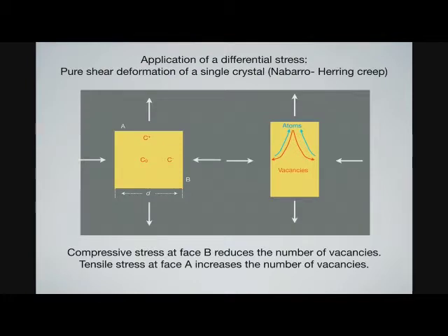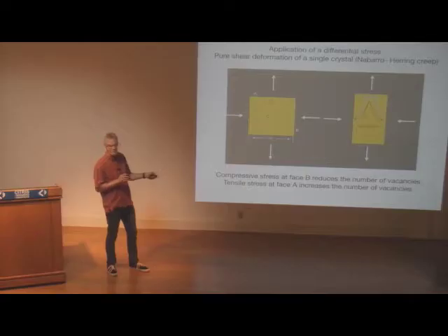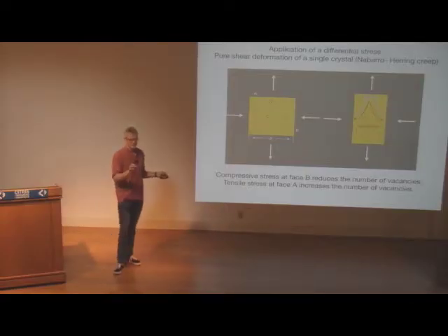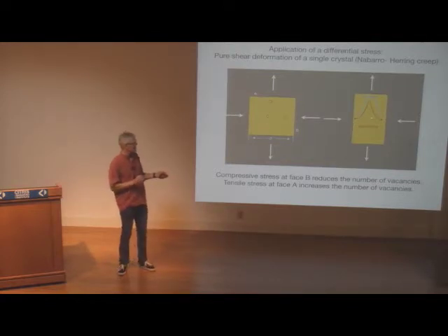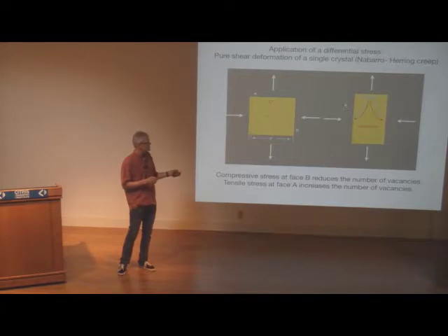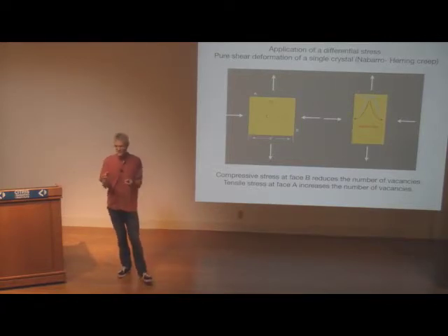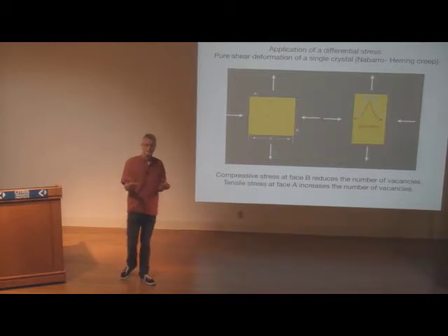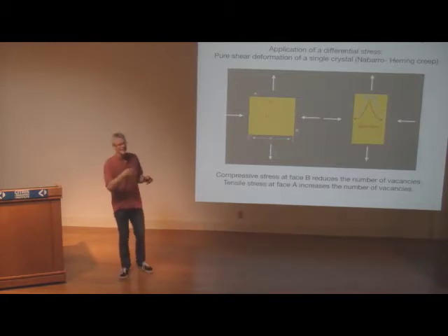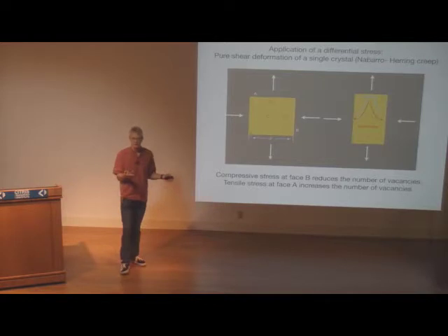If here you're diffusing through the lattice, it turns out that as grain size increases, it becomes energetically favorable, or it's faster, basically, to diffuse along the grain boundaries. And that's the reason why I started talking about grain boundaries. Grain boundaries are more disordered, so it's a fast diffusion pathway.